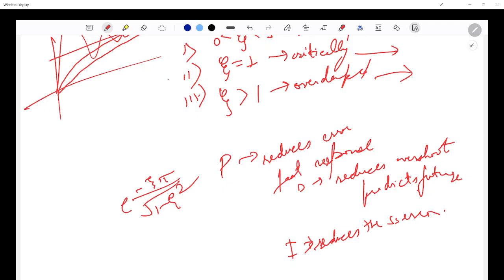So if you have a large ki, it might lead to instability because you might try to decrease the steady state error, but a large ki does not help. The system is not going to achieve it at all. And a large kd means that it is sensitive to noise. Okay, so I think all of this is clear to you. We can move ahead with a few questions.